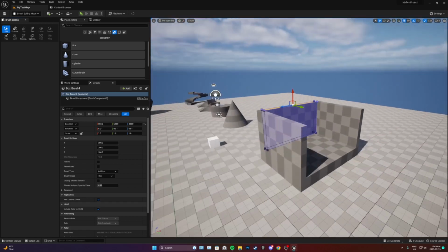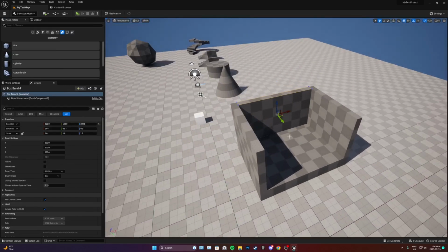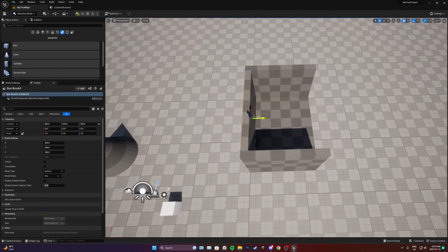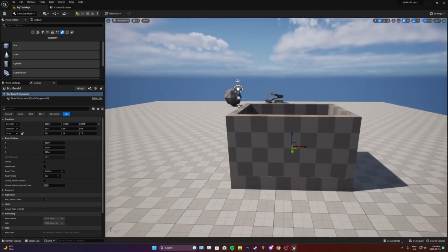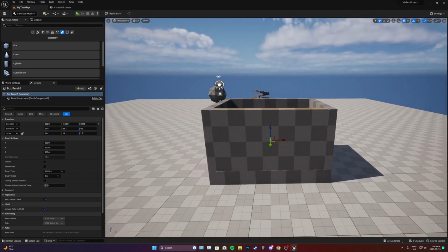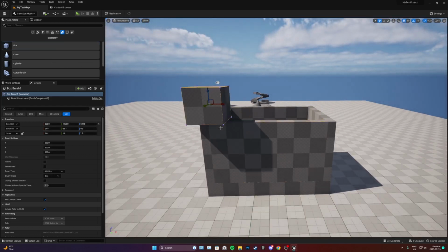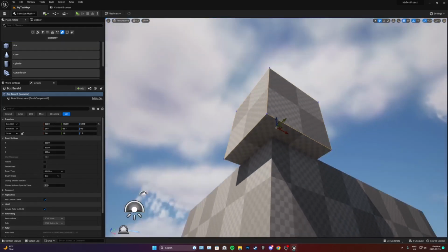But once I have this little box here, I am going to make a front wall. So I'm going to hit Shift 1 to go back into move. And once I move around, it'll reset my pivot point, which is really cool. I'm going to hold Alt, left mouse, and drag from the y-axis and make that front wall. Now, I'm going to do one last thing, which is the roof. To do that, I'm just going to drag out a box again. And I'm going to place it on the corner like that. It actually placed exactly where I want it, which is nice.